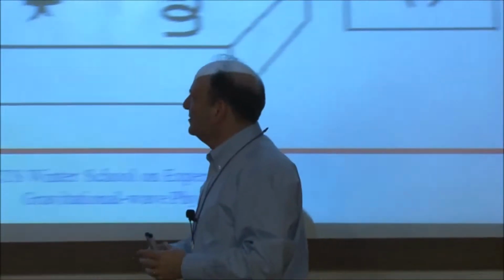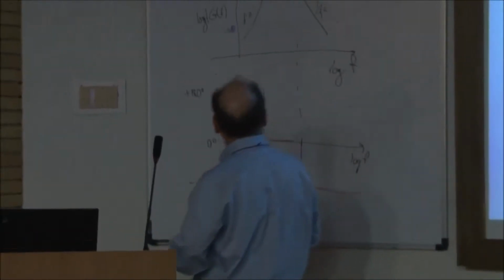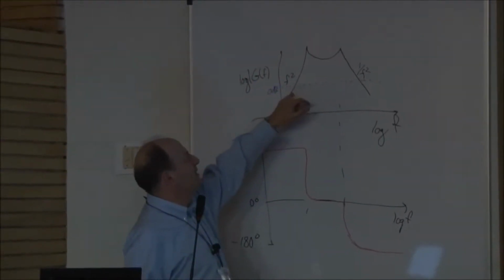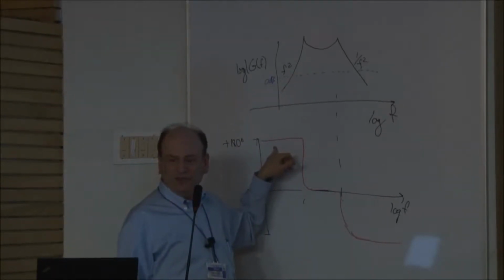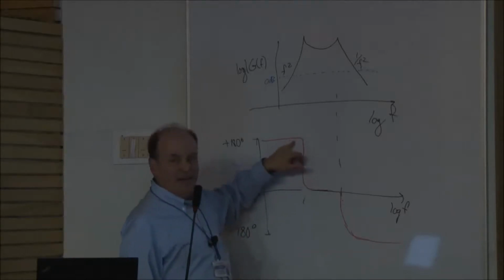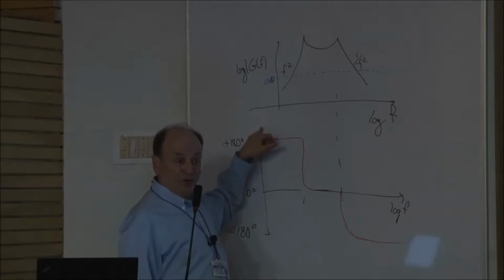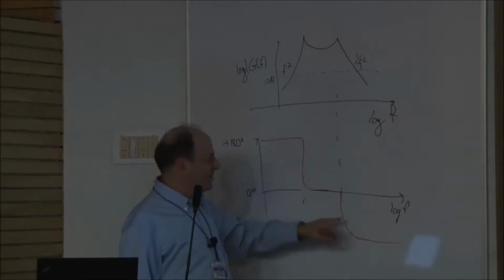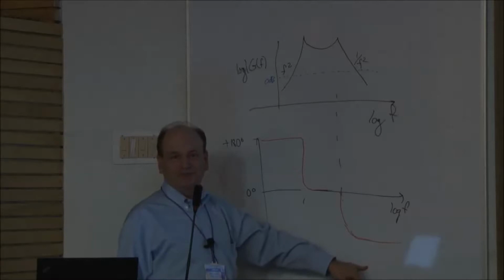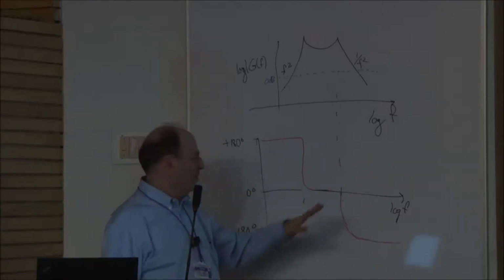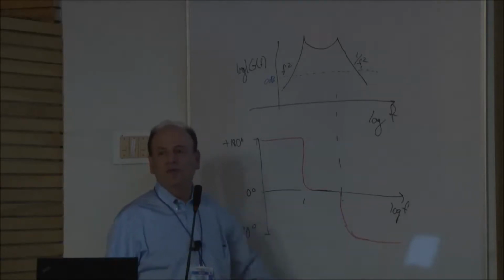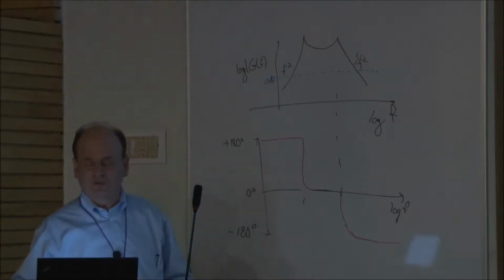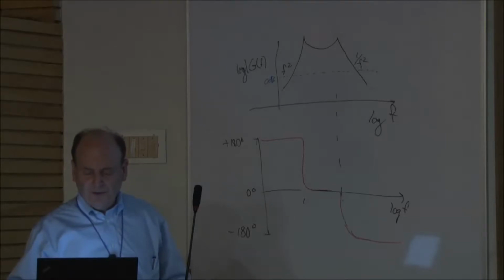Now, in a moment, let's come back to this when we talk about stability, because there's something that's very twitchy about this loop transfer function, namely that the phase of the loop transfer function goes to the wrong sign, both at low frequencies and at high frequencies. This can work. It does work. But you have to do something a little bit more to make it well behaved and not just on the verge of being unstable because of those sign changes. I'll say a little more about that in a bit.